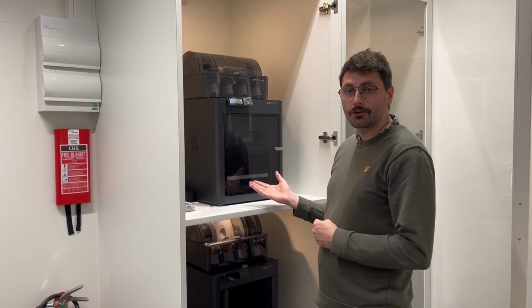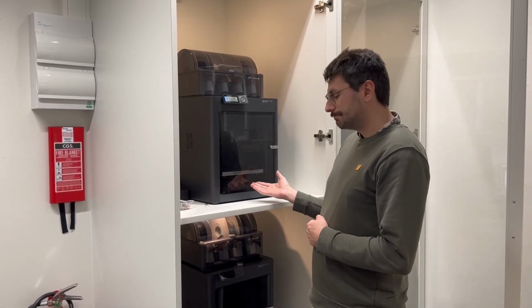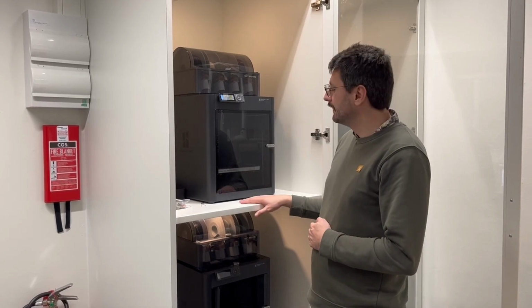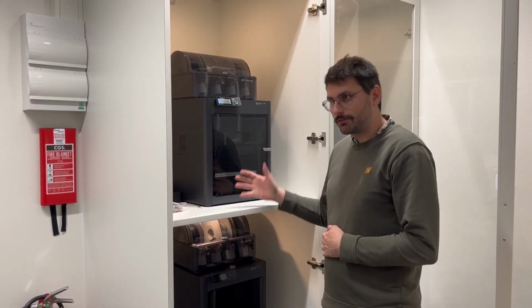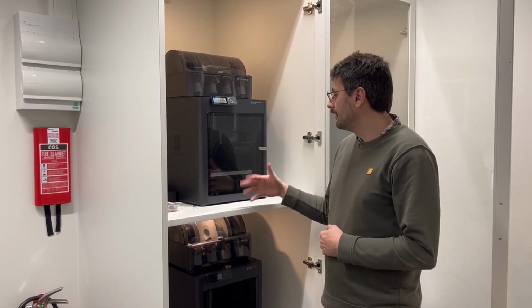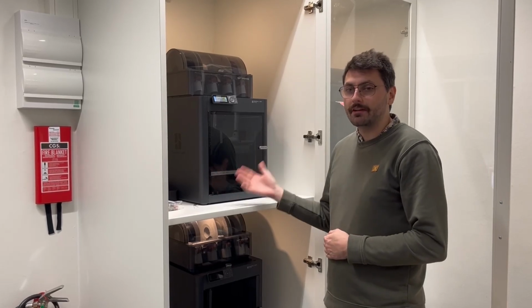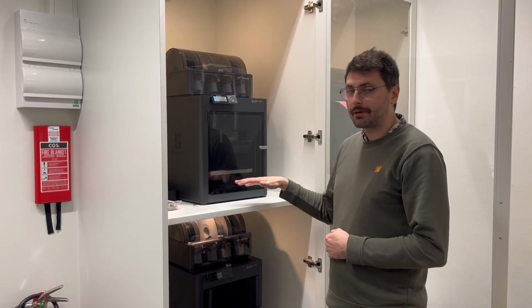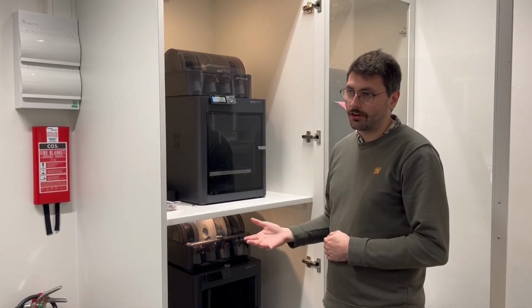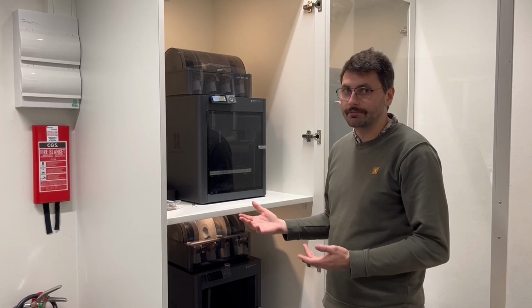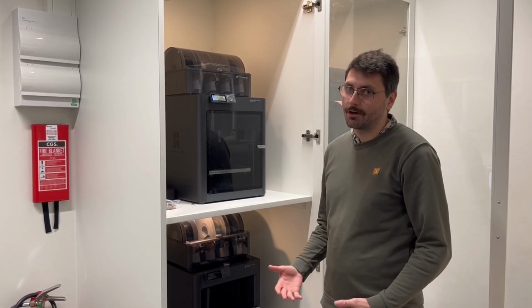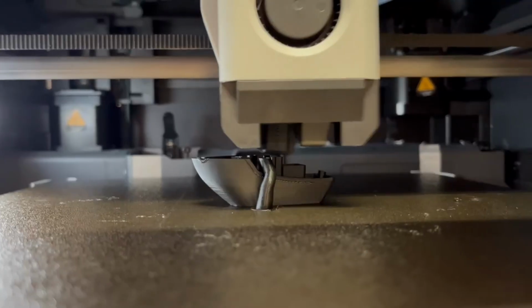Now the printer should automatically start calibrating, and you simply need to wait. It's good practice to wait the first 5-10 minutes, simply to see that the print adheres properly to the printing surface and doesn't fail early, as that is the most common time for a 3D print to fail.